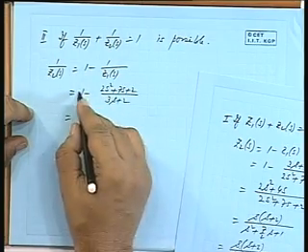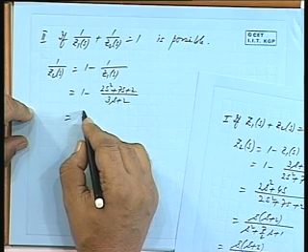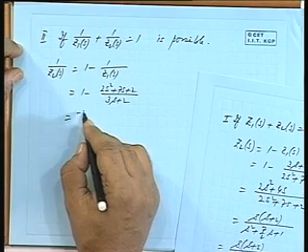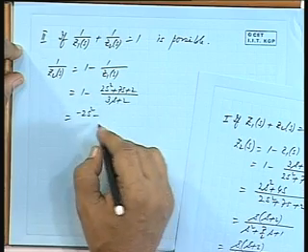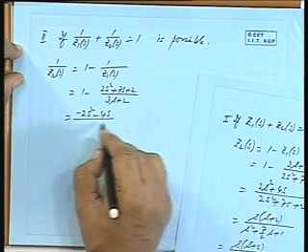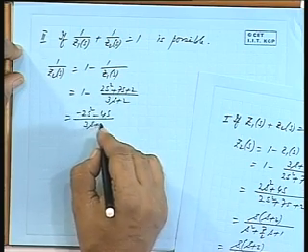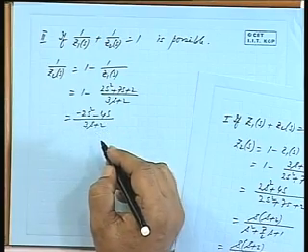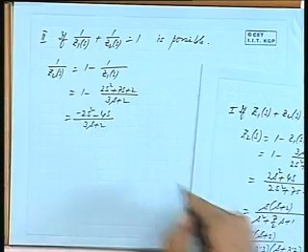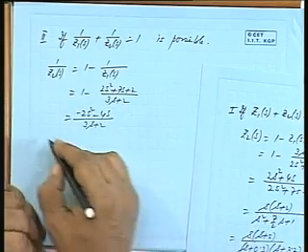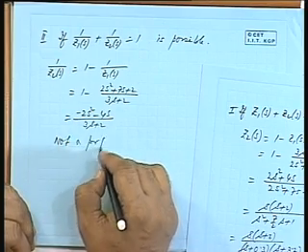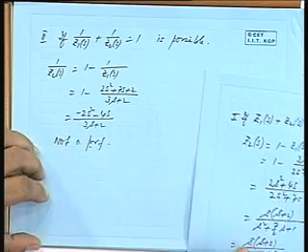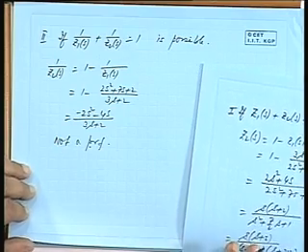So that will give me 3s plus 2 minus this. So obviously this is minus 2s squared minus 4s divided by 3s plus 2. You cannot realize this negative transfer function. So this is ruled out. This is not a PRF, so this cannot be realized.